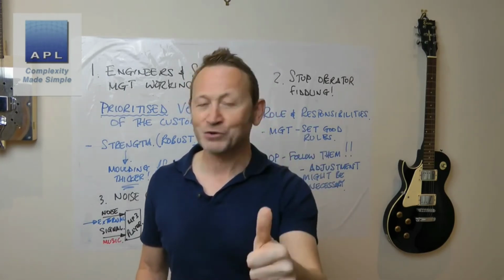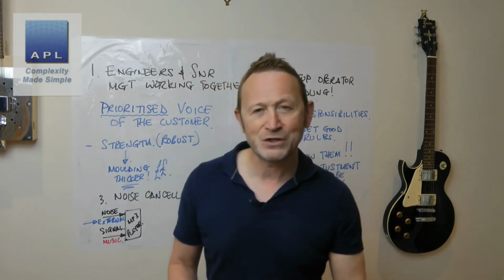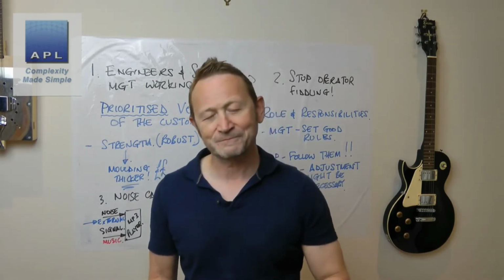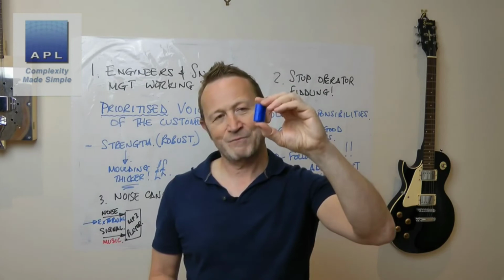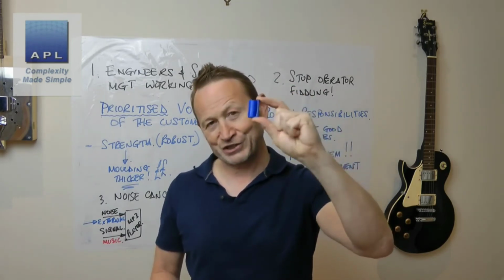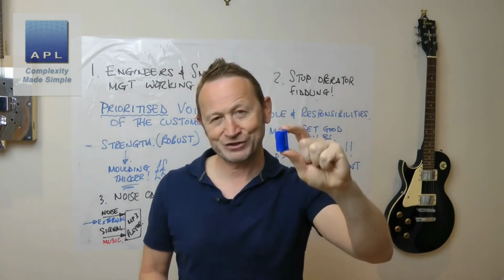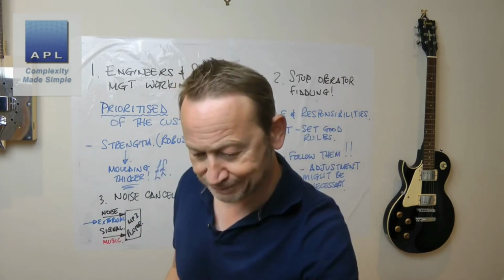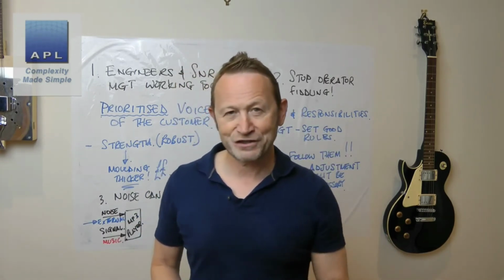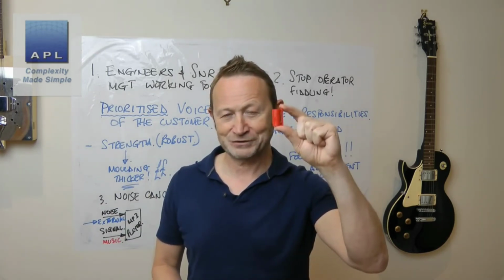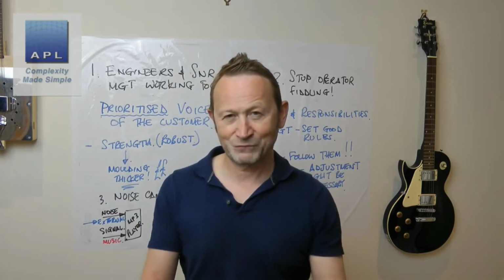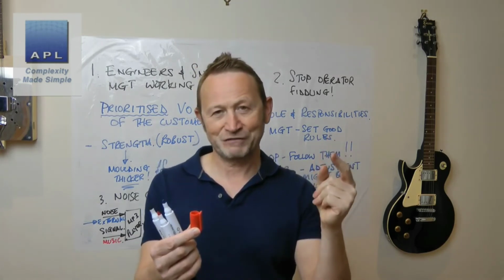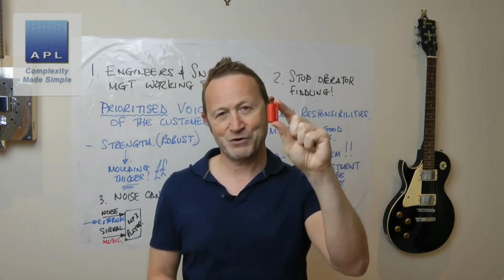Number one, we don't know the noise in manufacturing, and number two, the response is not instantaneous, because this is what happens. I make this one, maybe this one took 30 seconds in the molding machine to manufacture it. I then measure it, and by the way, I don't know which bit's signal and which bit's noise at this point. But then there's another 30 seconds till this one comes out. Where do you cancel the noise from? Where's the point where I have to inject some kind of electronic correction so that this one is okay?